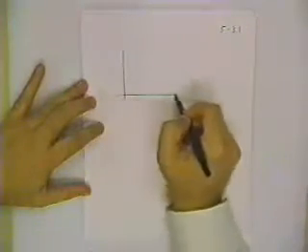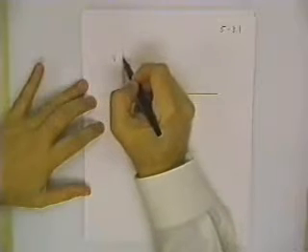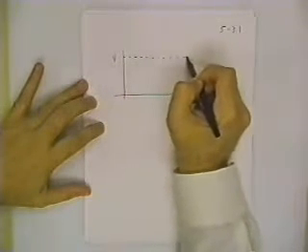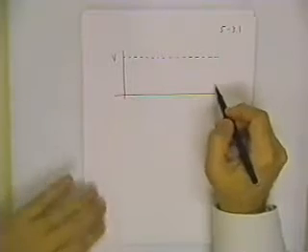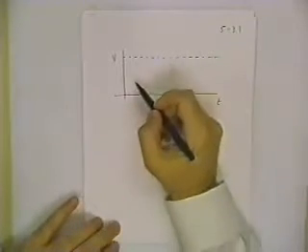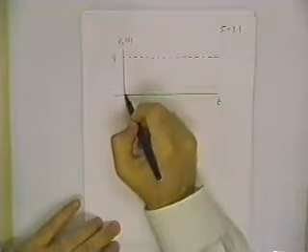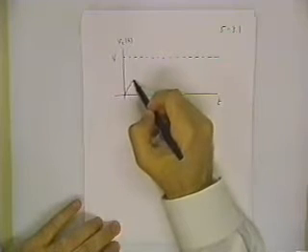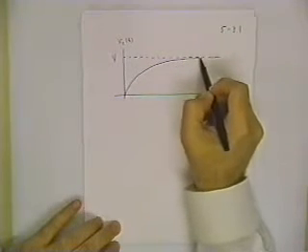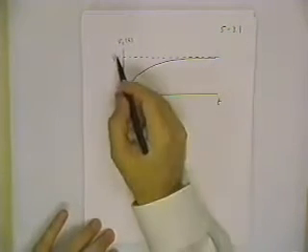And if we look at the sketch of this, we'll also see how the time constant comes into play here. For the capacitor voltage, for a charging capacitor, we've got an eventual steady state voltage of V, but we have to wait an infinite amount of time for it to actually get that large. Vc starts at 0, so this is Vc of t, starts at 0 and builds up, getting closer and closer, asymptotically approaching the final steady state value.